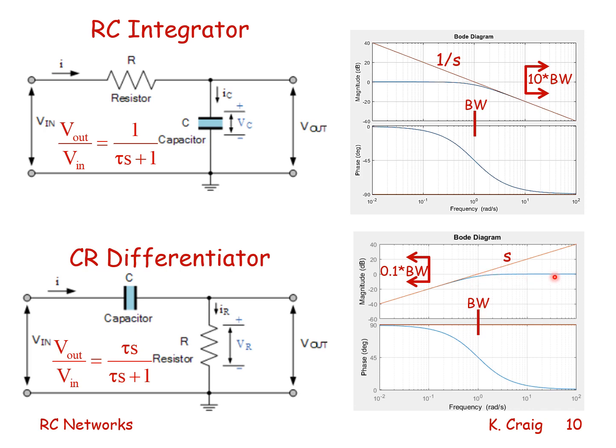And then it flattens out at, in this case, 0 dB. So at the bandwidth, which is 1 over the time constant, in radians per second, the amplitude is minus 3 dB of the steady state value, which is 0 dB, or the constant value at high frequency.